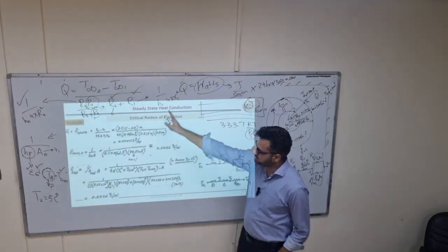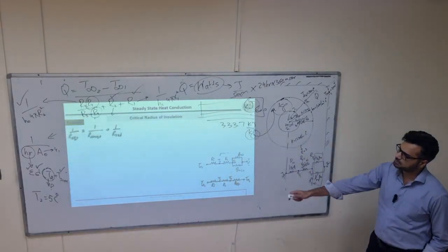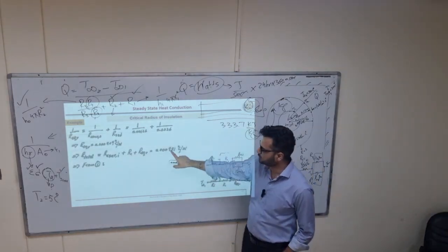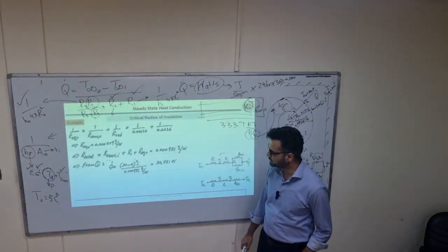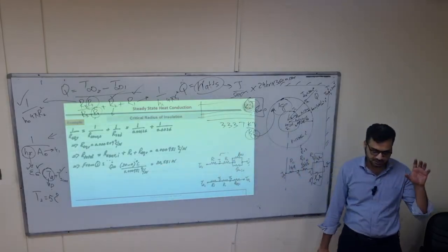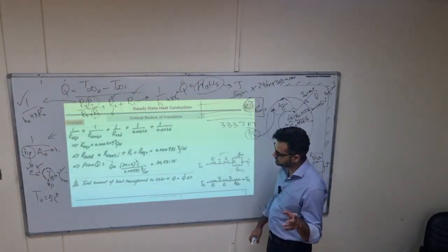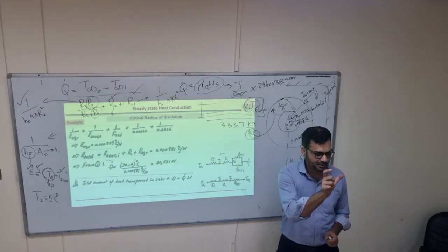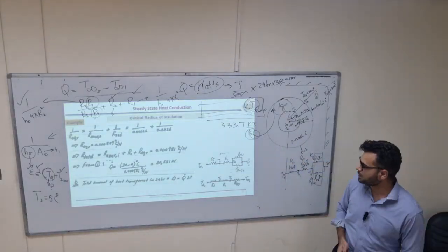So these are the resistances. All the resistances are calculated. Now use this equivalent resistance, okay. So this is the total resistance. Heat transfer, now we have calculated 30,581. Now we need to check T2, which we assumed. So how to check? Oh, he is not checking, he is directly calculating. Actually, his assumed value was already correct, that's why. But he will check it.